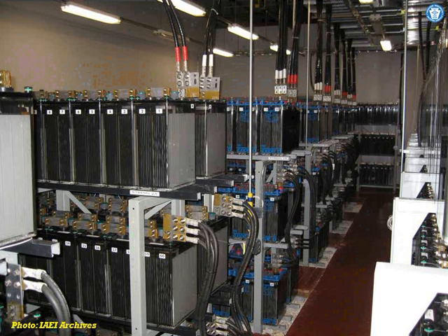So if your UPS production is 550 and your battery's production is 550, you can tie them together, and they're constantly tied together. They're just charging the batteries every time it discharges, and you draw the power through the UPS this way. The minute the power gets interrupted from the utility side, there's no switching mechanism whatsoever.